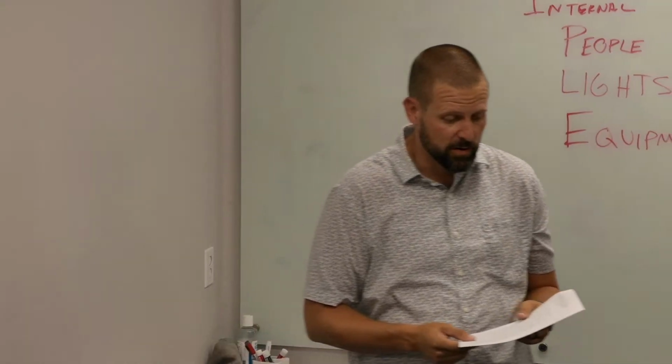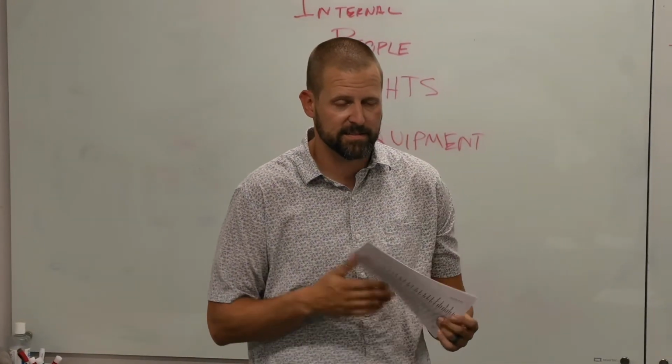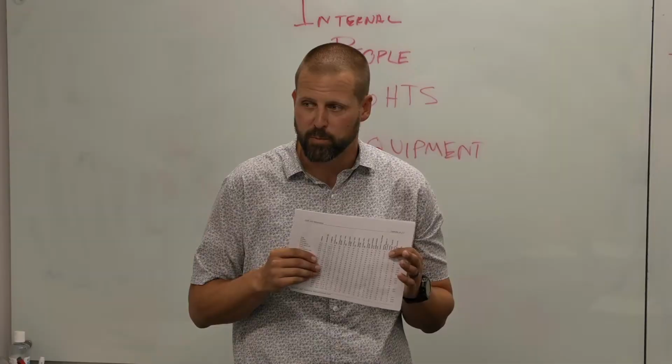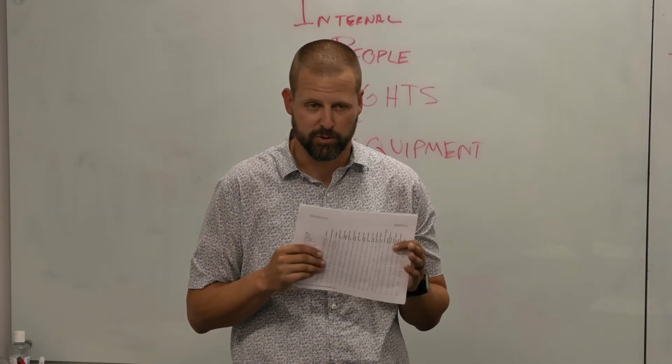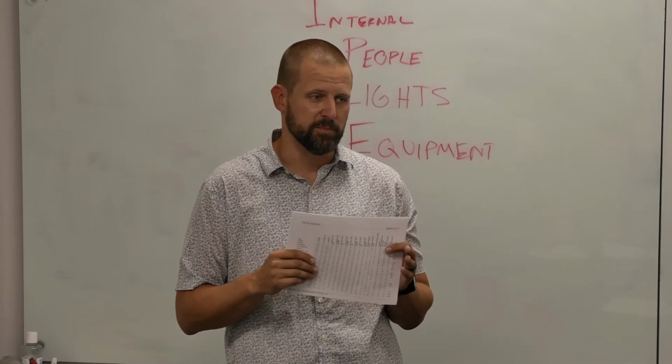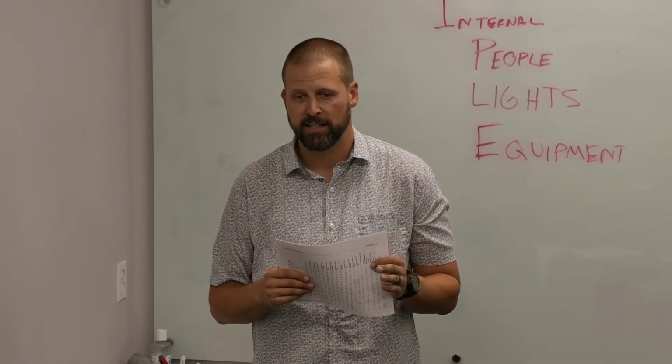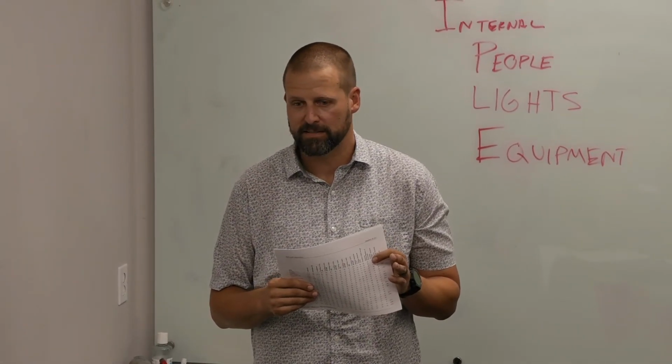We will talk about heating later, but there's heating temp on here. There's also other weather data that's not in this that will give you how dry it gets, like how many grains of humidity you see in the winter, and we use that to size humidifiers.